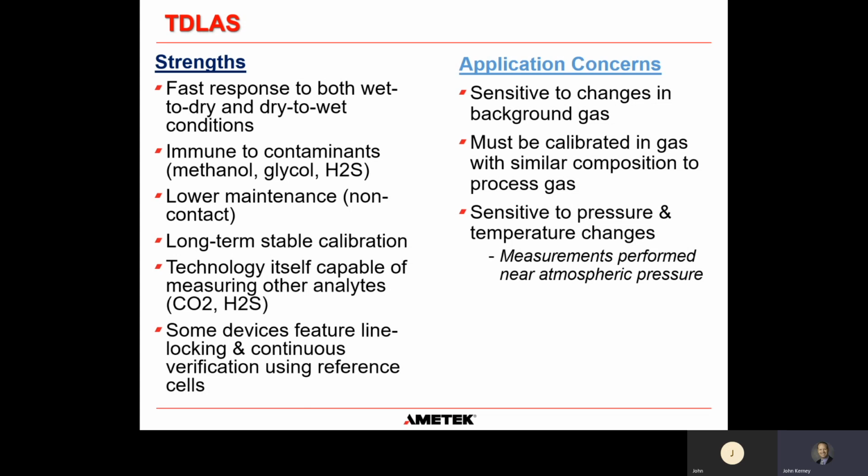They're very analyte-specific measurement devices. Because only light is touching the process, if you're touching the sample gas, they really have very little maintenance to them, unlike other technologies where the sensor contacts the process. In the case of TDLAS, only the light beam is contacting the process. So they usually have moderately higher capex, but lower opex over the long term.